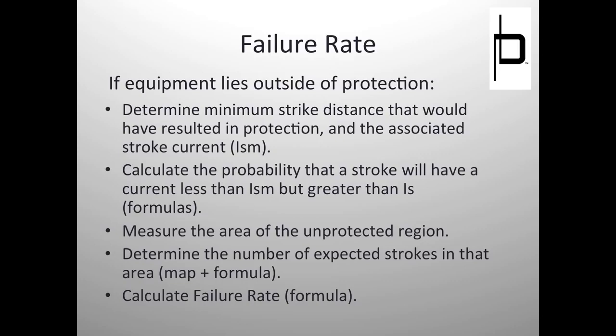Now, is that the actual stroke current of a random given lightning strike? Probably not. We don't know what it's going to be. The actual stroke current may be greater, may be smaller, and the BIL will absorb it. We've just defined our sphere based on the worst case.